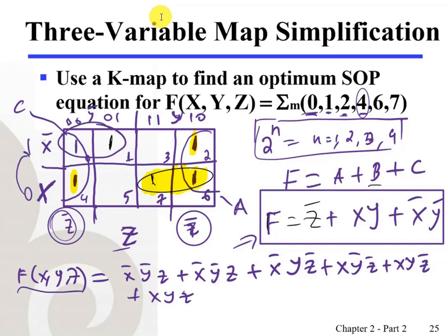So now the question is, given the following function represented in canonical sum of products, if you want to minimize or optimize this function in terms of cost, those input cost or literal cost, you may apply Boolean algebra techniques to minimize, and one may end up with different solutions. However, Karnaugh map allows us to find the optimum, right, very easily without applying Boolean algebra techniques. Well, we can check later this representation of our function is equivalent to the following. This is the optimized, let's say, optimum or best possible solution in terms of the gate cost. K-map comes very useful and handy.